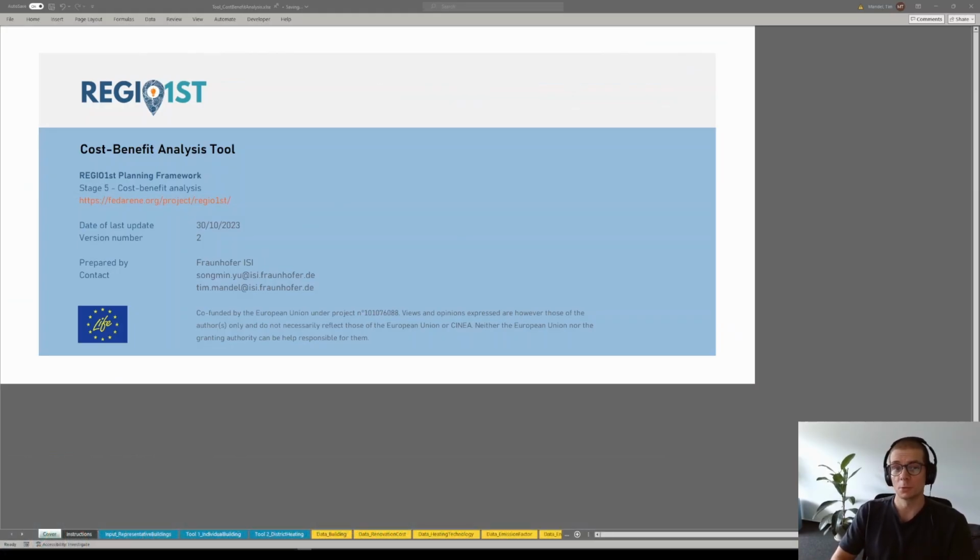In this video, we will walk you through the cost-benefit analysis tool, which is a part of stage 5 of the Regio1st framework that is designed to compare the costs and benefits of building renovation and heating technologies in line with the energy efficiency first principle. This tool helps you evaluate demand-side measures, in particular building renovation, and supply-side measures, such as different heating technologies like heat pumps. It calculates the cost of saving heating through renovation and the cost of heat supply, so allowing you to identify the most cost-effective solutions for your regional energy plans.